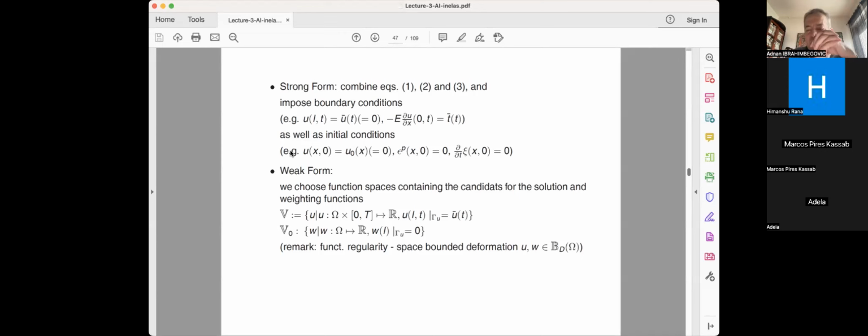So I was joking, if they can have beef that says produced in France rather than in the United Kingdom, you can have a sheet metal which says produced by lamination process in this direction, and then you can have the definition of this plastic deformation precisely defined and quantified. And then you build on top of that, because this was the initial condition for your sheet, and you can then orient this rather much better than the Hill criteria, which at that time was used heavily.